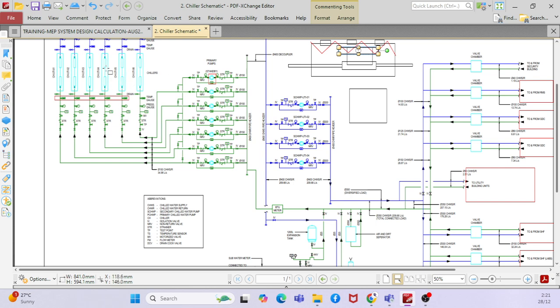Now this is the circuit. As I said, you have a chiller, then you will be having building side cooling equipment like AHU or FCU. Then you will be having a pumping device. You have a chilled water pump. Say for example, you will say building pump, and also you will say primary pump. The primary pump is normally required for the chiller, to make sure the chiller gets proper flow. That is why you have a primary pump. Clear? So that is called primary pump.